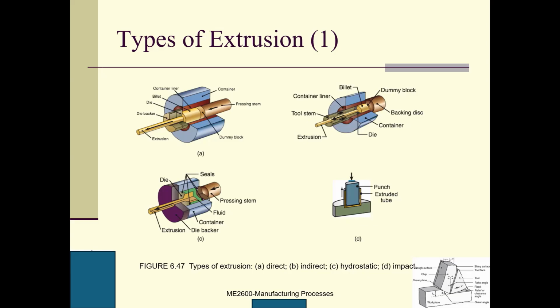Originally, my raw material is so big, but because there is a pressing stem, this guy keeps pressing. This is a small orifice, and you can just think of this as a liquid. So this liquid is coming out from this orifice. I'm saying liquid in quotation marks. So this one is extrusion, right? This is a direct extrusion because of the very huge pressure from the bottom. So this guy can flow from this orifice, from so big to so small. So this is called the direct.